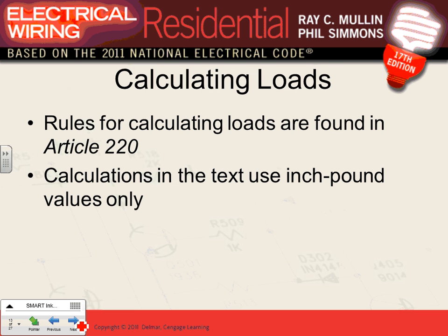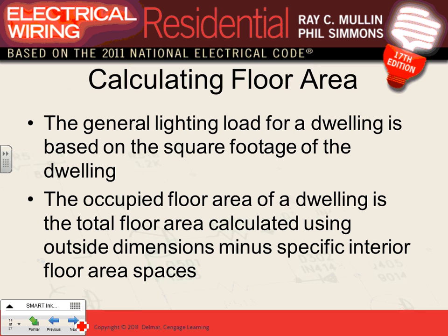I'm going to refer the calculation, guys, based on this into a different thing. We're going to be doing calculation based on Article 220 for the whole apartment, so I'm not going to mess with the calculation this time. When you do the calculation, though, you take the square foot of the building and you measure from the outside perimeters. Only the habitable places are included, or any space that's adaptable for habitable space. So unfinished basement, you count it because you could finish the basement. The portion that could be finished for habitable, that should count.